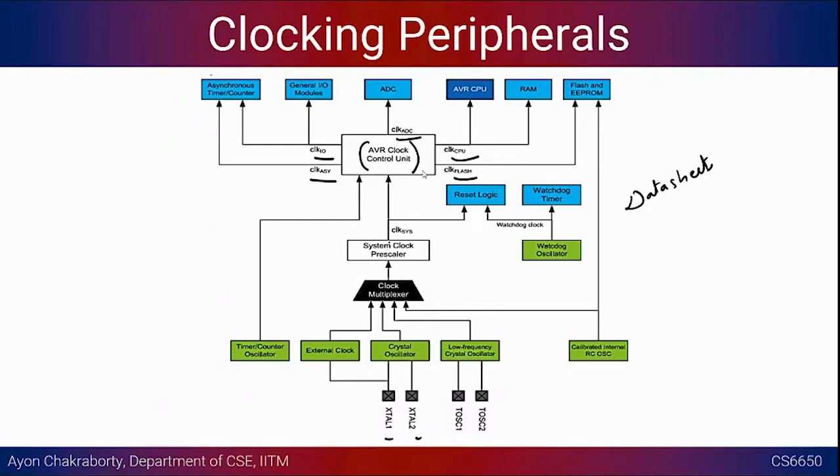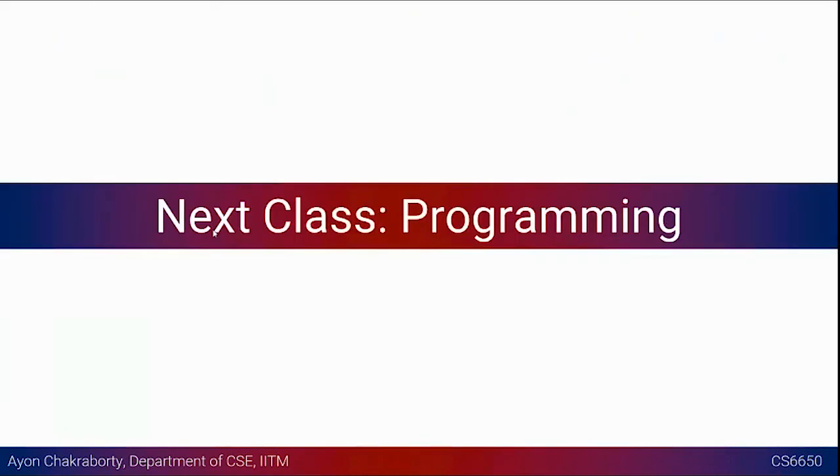So this is a small takeaway. Often we might think that if you are giving a 16 megahertz clock, everything operates at 16 megahertz. That is not true. There is this very important concept called prescaler that determines the maximum data rate for that particular peripheral, and in that way you request the data. If you are requesting more data, the device is not going to answer. So with this I'll wrap up.